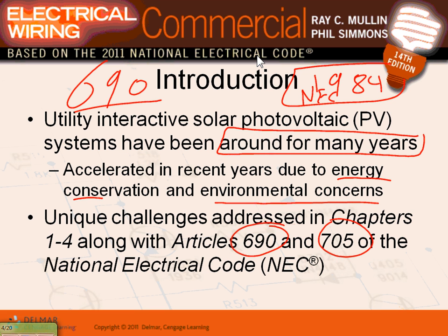How do you tie two? You have the grid and you have a power producing facility. Tying them together requires some marking and disconnecting and synchronizing that you have to do, and that's basically in Article 705. I will touch on 705, guys, when we do paralleling for the next project.